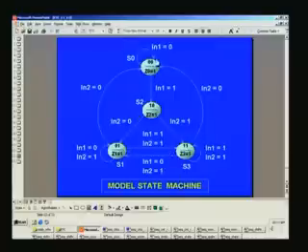For example, if it is in S0 and so long as the input is 1, you remain there, and you also light an LED. Any output can turn on the output Z0 here, and for every other state you have Z1 representing the same state. So based upon the input conditions in 1 and in 2, it goes from one state to another. We can see one of the waveforms here.